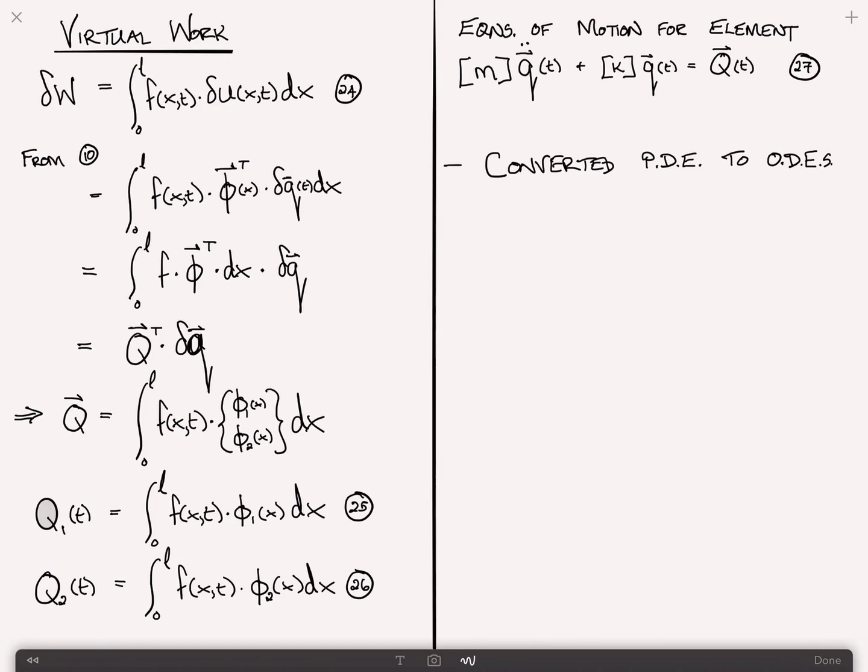And we did this by assuming a spatial distribution. Instead of using the exact solution for the spatial distribution, we assumed it by picking an admissible shape function. So you write that we used admissible shape functions, phi i of x. And by admissible we mean, as we showed, that the shape function should be 1 at its own node and 0 at all other nodes.